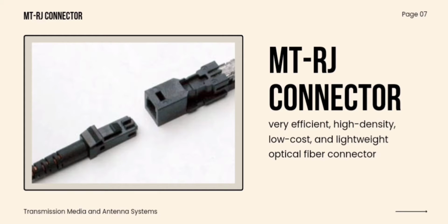However, this is smaller in size and consequently lower in cost. It is slightly smaller than a standard phone jack and is very easy to connect and disconnect. Compared to older types of fiber optic connectors, the MTRJ offers lower termination cost and greater density for cable management hardware.